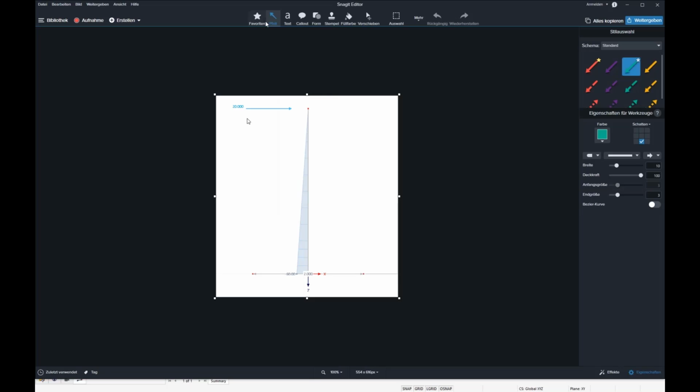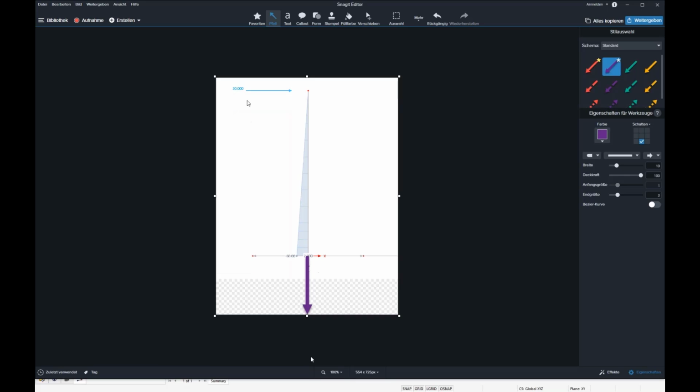What means I draw this arrow here and say, okay, here we have a vertical component but with a specific length, 26.75 kilonewtons. But we also have this bending moment of 60 kilonewton meters, which maybe could be visualized as a pair of forces. What means I have here a pair of forces in this direction.